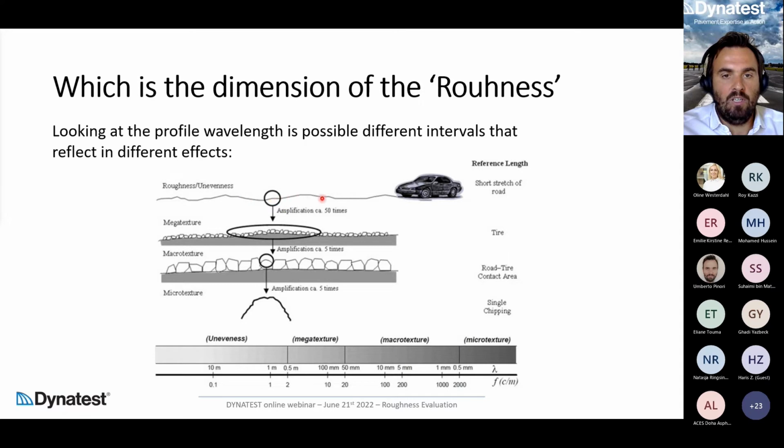So you have small deviation or small bump on the profile road. And this is usually what affects a car. Then you have a slight deviation of the true planar, usually between 50 millimeter and 0.5 meter wavelength. And this is usually something that affects the tire dynamic.